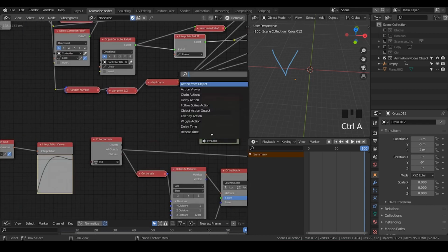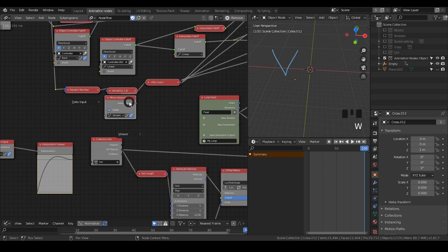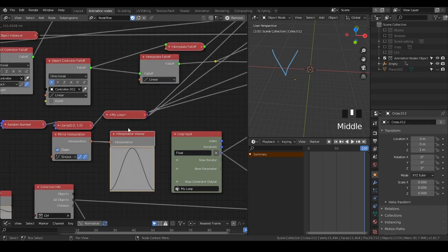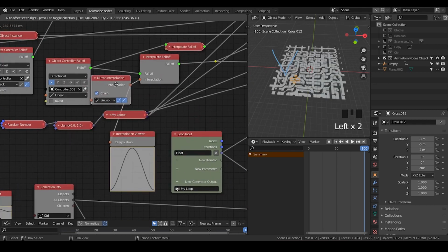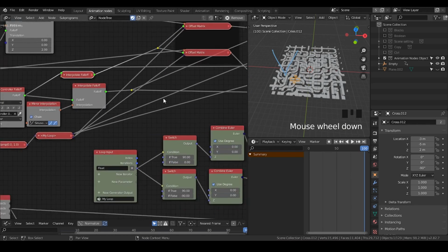There's a node which is called a mirror. You can change that type to sigmoid, and change the interpolation. You can see how it actually works. It goes to maximum, but it goes back to the initial state, and you can change its interpolation. So I'm going to put this mirror to the place. Now everything has recovered at the end, and this is how it essentially works.